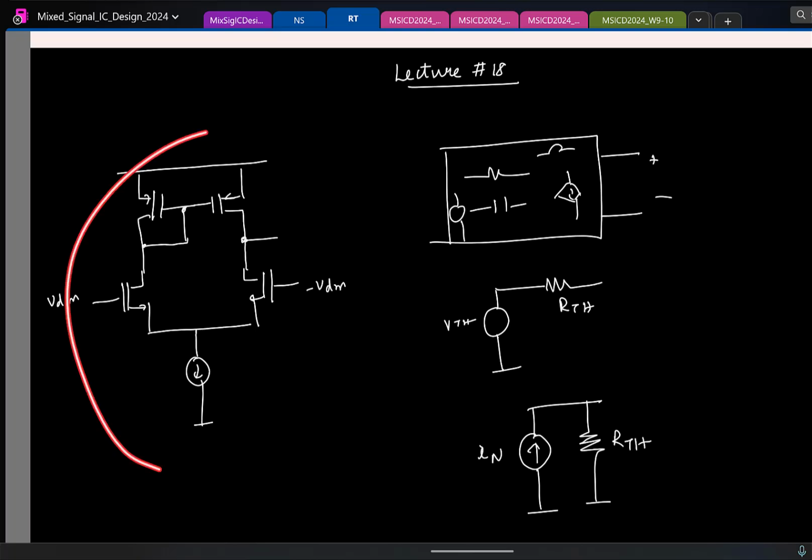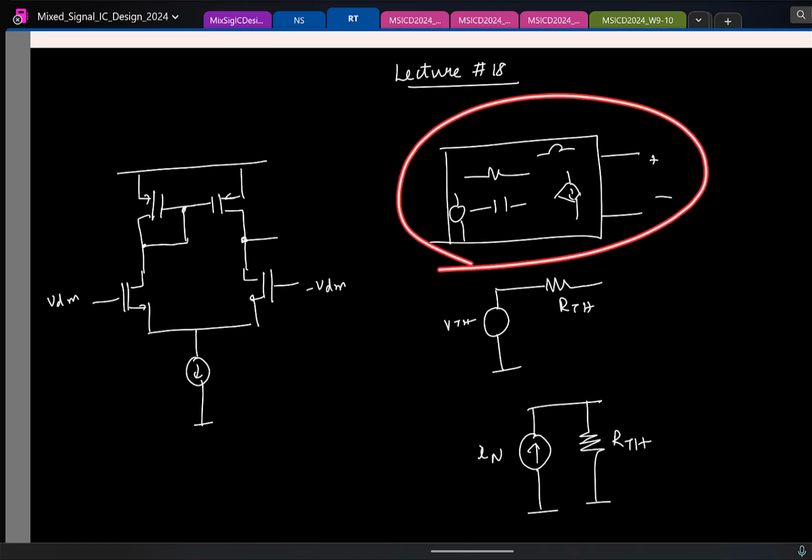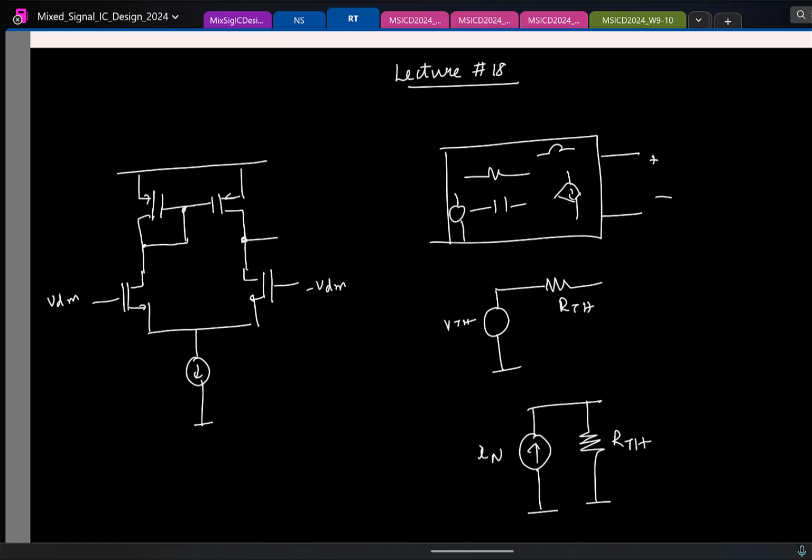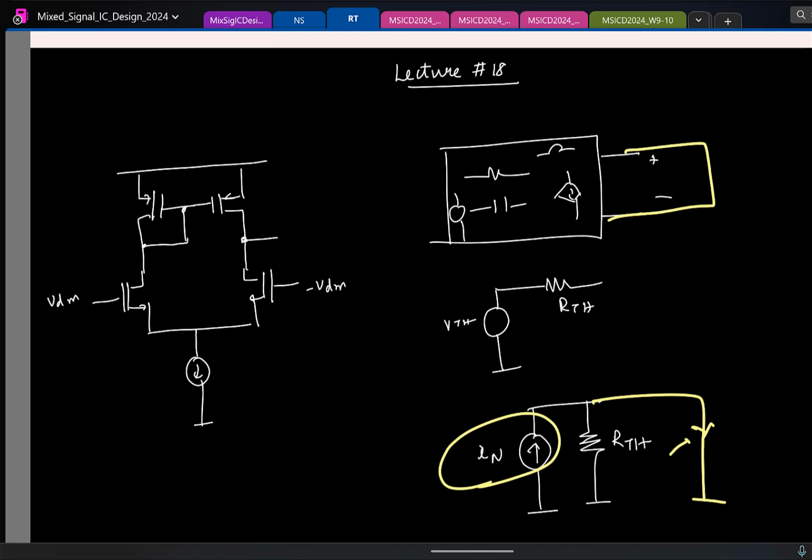So here this is also a linear circuit like this. In principle you can find the Norton equivalent current and find the equivalent Thevenin resistance. To find the output voltage, I just take the product of these two. And to find the Norton current, what would you do typically? This is the network, right? If you want to find the Norton current, what would you measure? You short circuit the output side. That makes sense, because if I short circuit this, all of this current flows here. So you find the short circuit current, that gives the Norton current, and you find the effective resistance looking in, that gives the resistance, and you take the product. That's also something you can do.